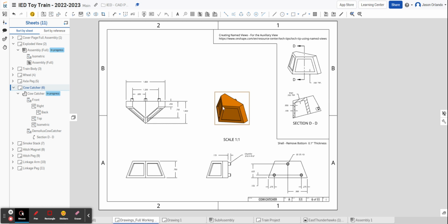Now, these little recesses on these angled surfaces on the front, little trapezoidal recesses, we wanted to understand the exact dimensions of that. And so to dimension a feature, we should be looking at it in its true size and shape, so straight on. In all of these views, we're not looking at it straight on, so the phenomenon of something being foreshortened is what's happening. And we won't get accurate dimensions from Onshape if we try to dimension anything there.